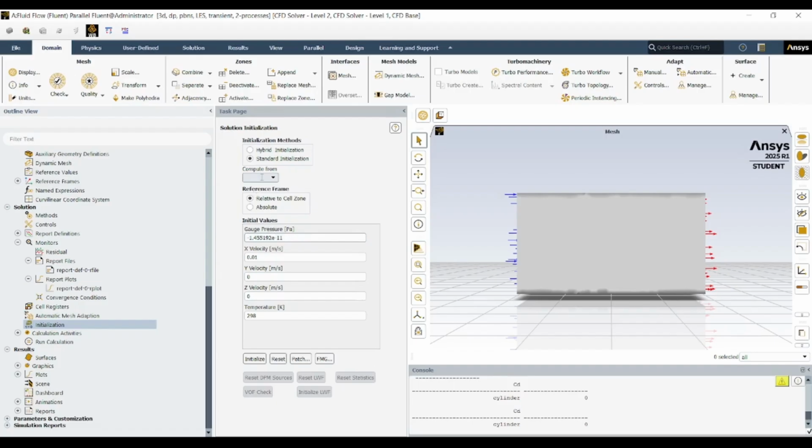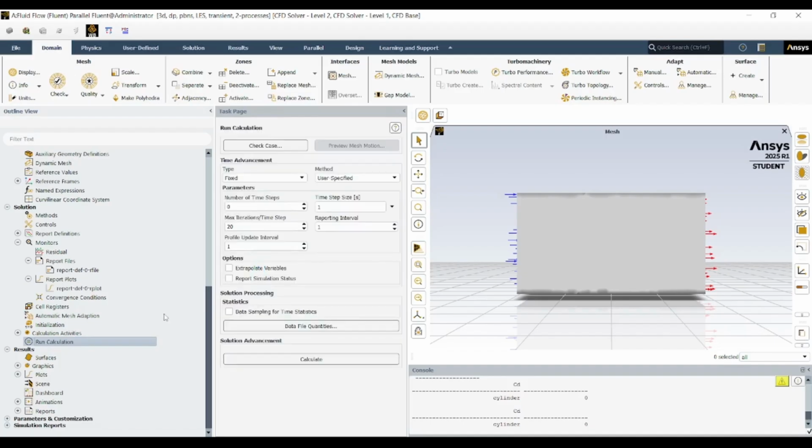This plot shows how pressure drops from the stagnation point to the sides and then rises again in the separated region. Comparing this Cp distribution for laminar and turbulent simulations helps you see how turbulence delays separation and lowers drag by maintaining attached flow longer.